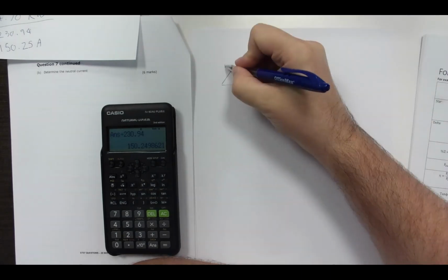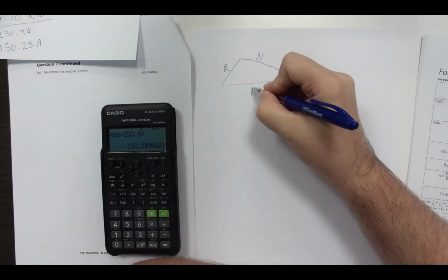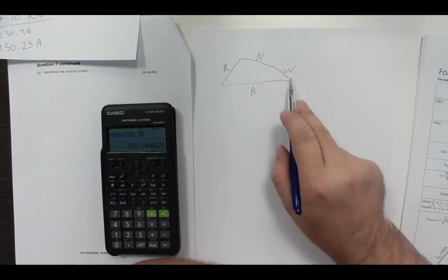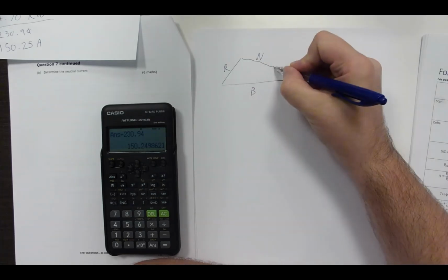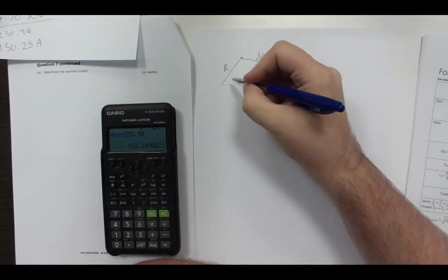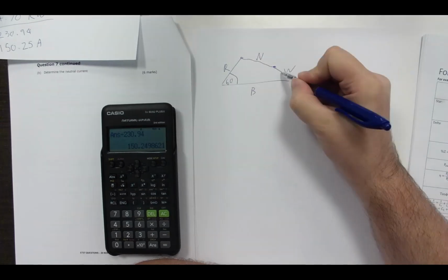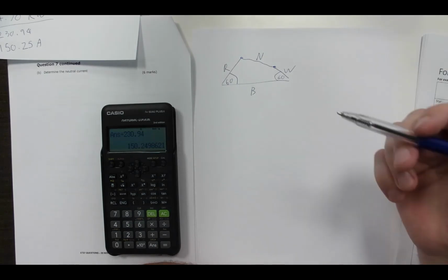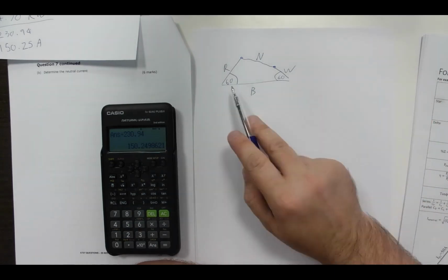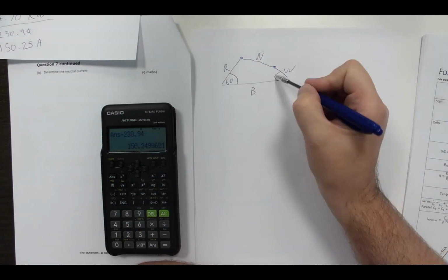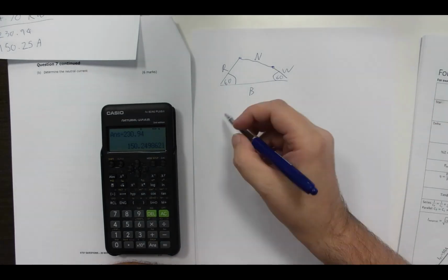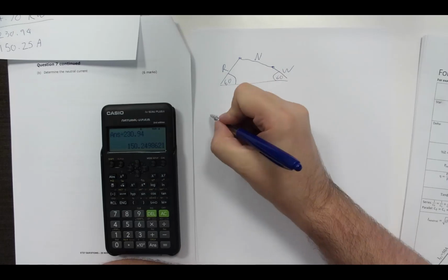So we've got red, white, blue, it doesn't really matter on the three, it's just longest, second longest, third longest type of thing. And then our point from there to there is our neutral current. This is 60 degrees, this is 60 degrees. It's an equilateral triangle, so if all three matched, you would have zero neutral current, and that's how balanced looks. But to use this one, we actually have to calculate our individual values.